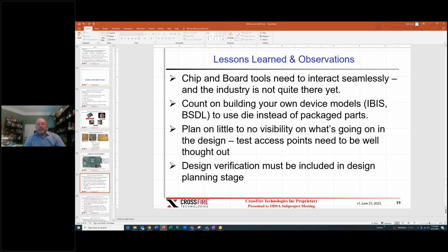The trick to doing that was there's a test enable pin on the DDR4 that you need to be able to make configurable, and work out how, in the system, to get it into test mode and out of test mode. It's one of the things that sounds simple, but you've got to think through carefully while you're booting up the device.